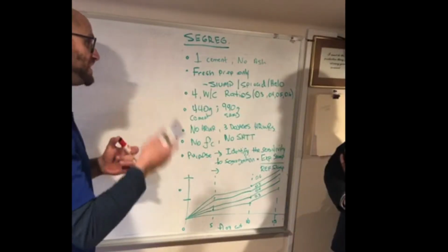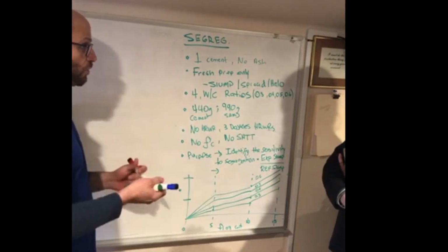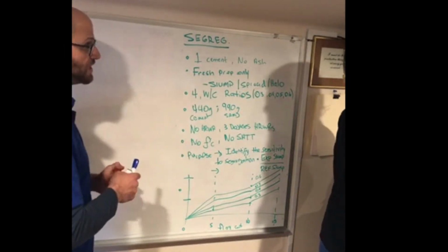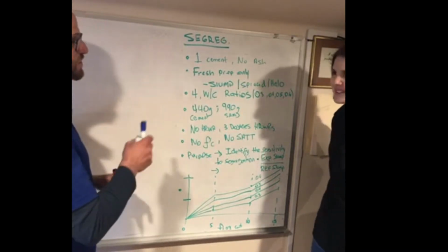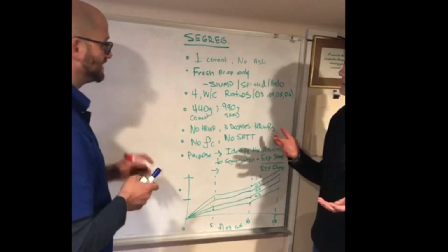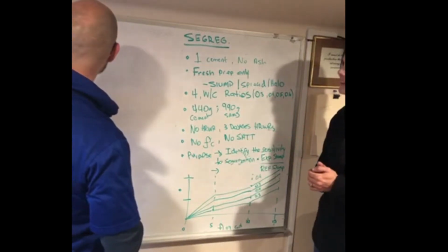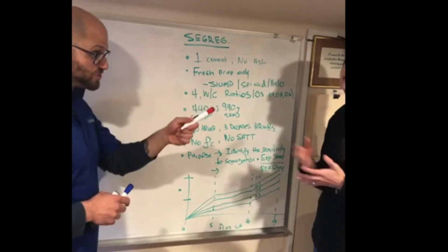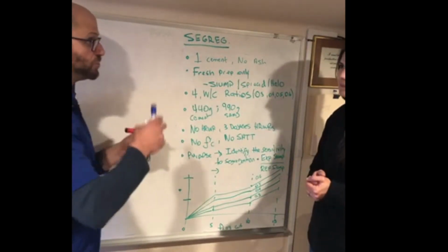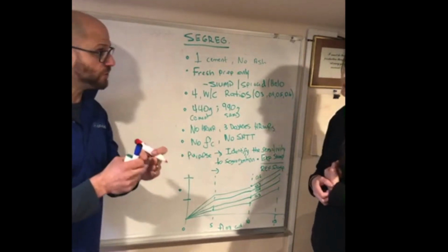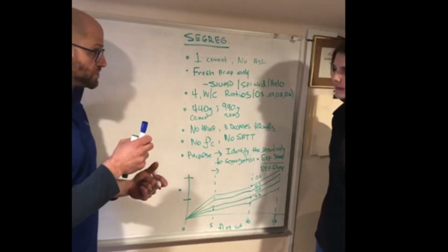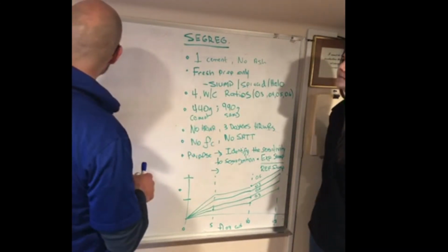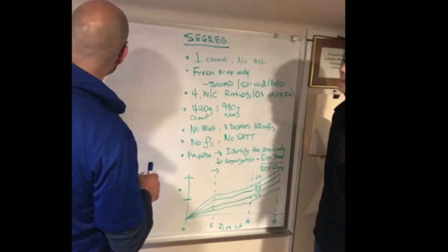Okay. So, this study is on segregation control or segregation destabilization, is, I guess, a shitty way of saying it, but another way of saying it. Do you get that? Yes, I do now. I was asking, what exactly does that mean? And the answer is, so what's the simple answer of it? When the water pulls away from the concrete. So, close. Or cement. So when the paste pulls away from the aggregate, that the paste is so fluid that it just drops out of solution, or when you do your spread, you'll see this nice halo effect. So that's when paste pulls away from ag.